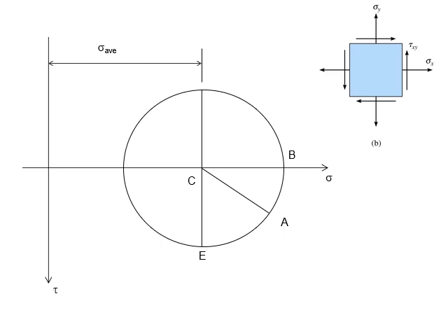So you tend to draw the shear stress axis towards the left of your graph paper if you use a graph paper. Otherwise, just sketch a vertical line on the left of your plain paper. And then you have your horizontal axis right in the middle. Okay, and that represents the normal stress.